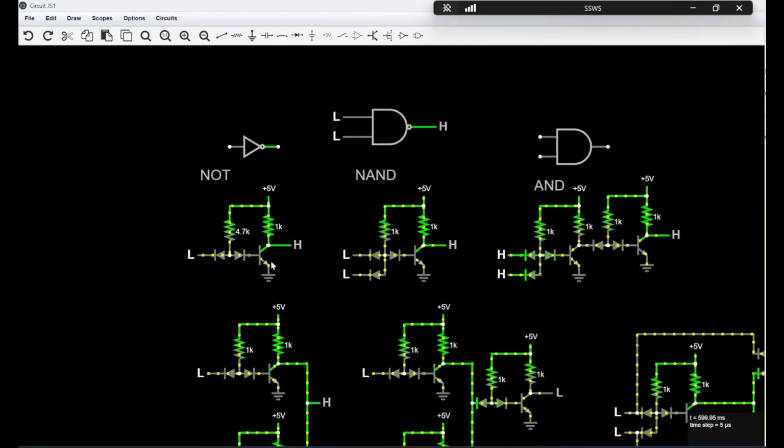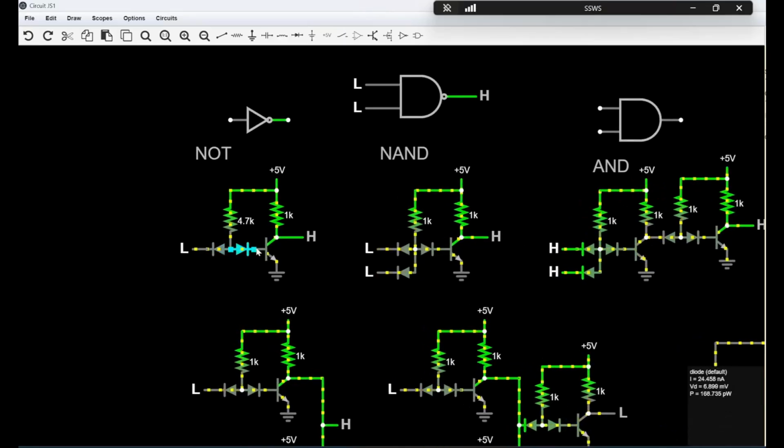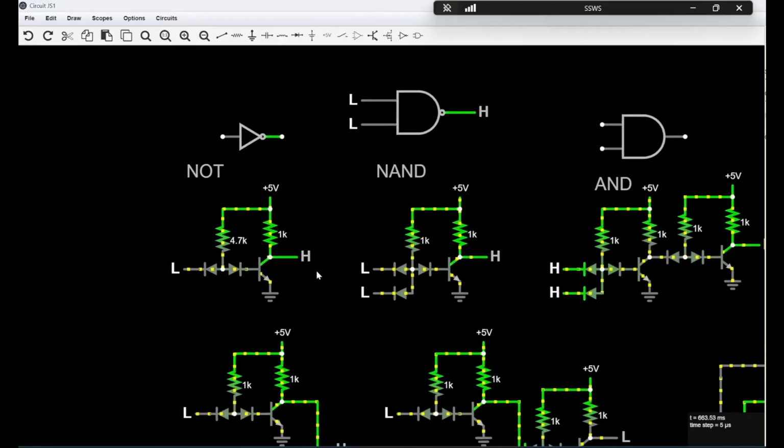So when you have a transistor, and then some resistors for keeping the current low so we don't blow it up. The logic in diode-transistor logic actually happens at these diodes here. You'll notice we have a diode in reverse bias, then another diode that leads into the base of our transistor. These values actually aren't the right values, but it doesn't really matter right now. Usually you use 4.7K, maybe 10K as the upper limit for diode-transistor logic, depending on your supply voltage.